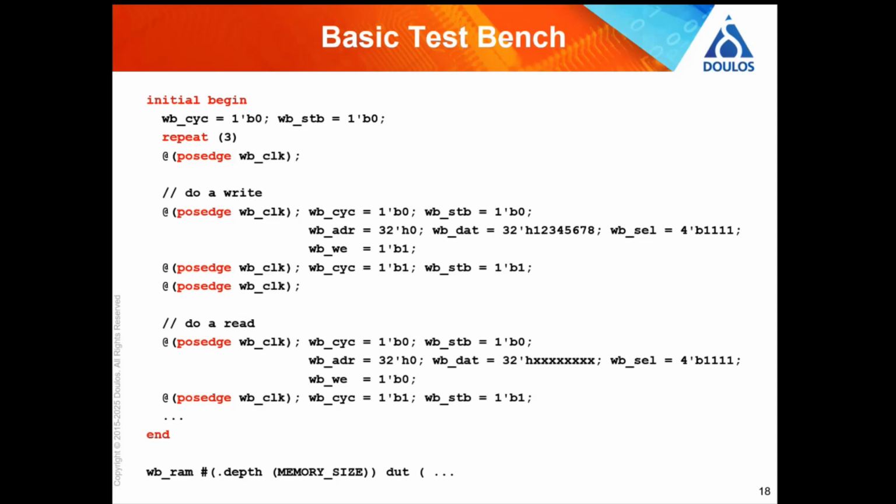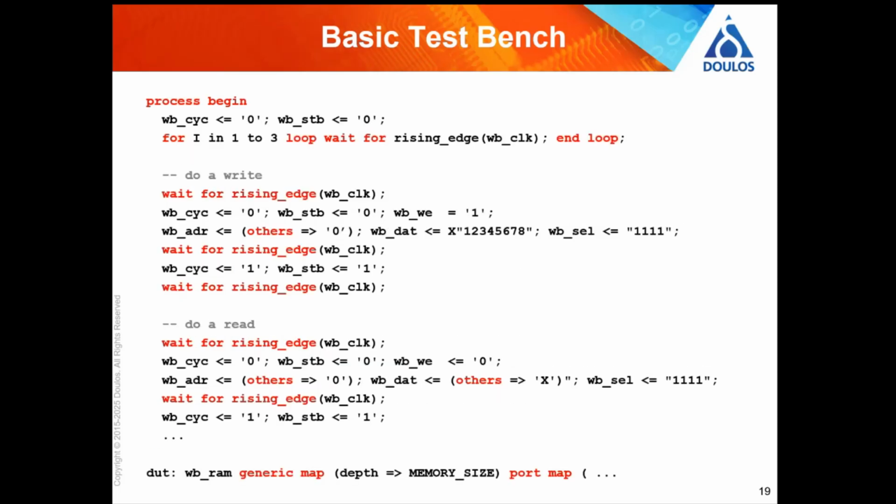Uniquely in this presentation, I've done the same thing in VHDL. So if you're familiar with VHDL, here is exactly the same thing in VHDL. We're starting by waiting for 3 edges on the clock, and then you can see, just with a different syntax, we're doing exactly the same thing. We're manually driving the inputs to the design under test.